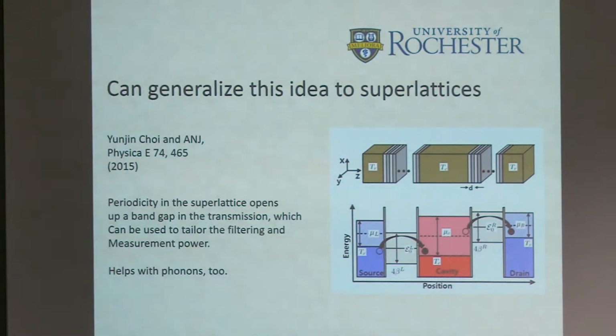And the phonons are this parasitic channel of taking heat from hot to cold without having it do any nice work for you. And people always tend to sweep this under the rug. But this is, of course, a really big problem. And so you have to solve this problem to make a practical thermoelectric. But these superlattices, actually you can study the phononic band structure of those as well, and those tend to inhibit the phonon transport. So this could also be a good way of inhibiting phonon transport.